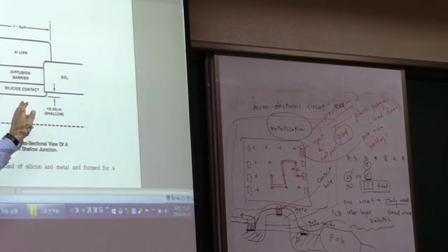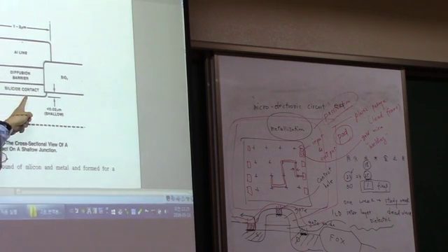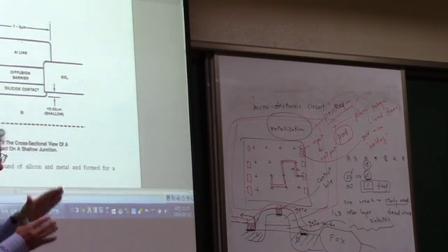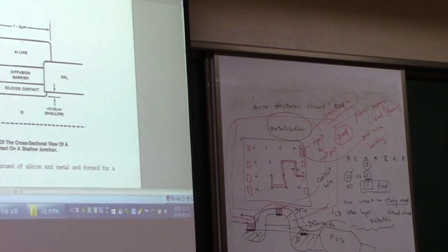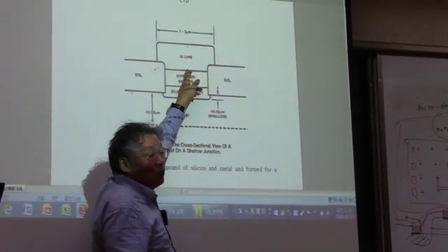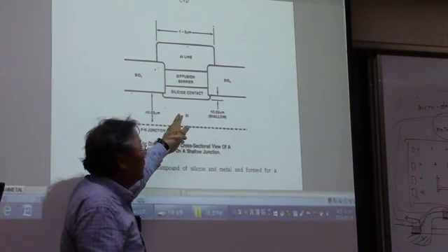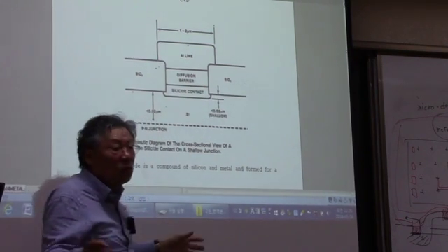We form a silicide. We are going to talk about why we need that silicide in a minute, but we make a silicide first, and then we have to have a diffusion barrier. And that diffusion is the diffusion from this dopant element, or the silicon itself, to the metals, or the metal aluminum. If you use aluminum, then the aluminum is going to be diffused into this silicon if there is no diffusion barriers.